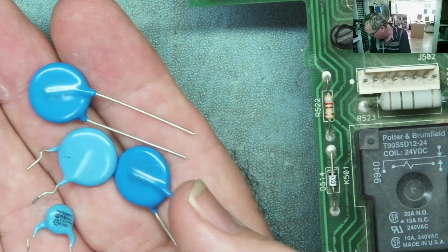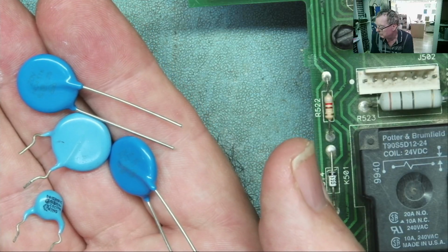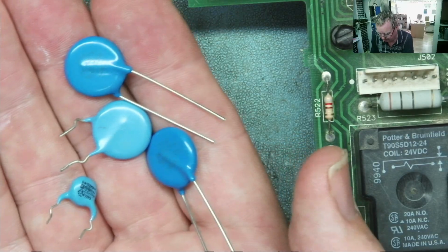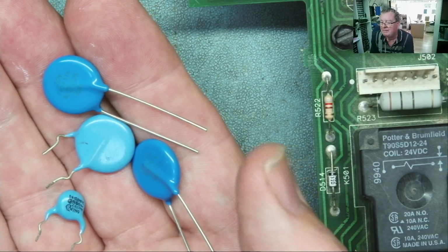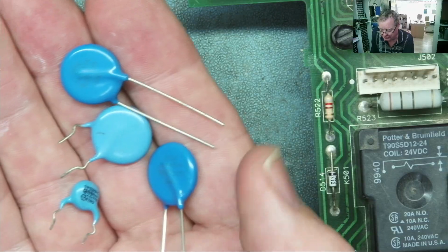If you're not sure whether your circuit has MOVs or NTC thermistors or both, it's also very easy to tell by looking at where they are in circuit. And I'll just show you where these are commonly found. Both these components are generally found on mains powered equipment, but they don't have to be. We can get MOVs that react to lower voltages, say 48 volts or above or something. So they can be on lower powered devices as well, or rather lower voltage supply devices.